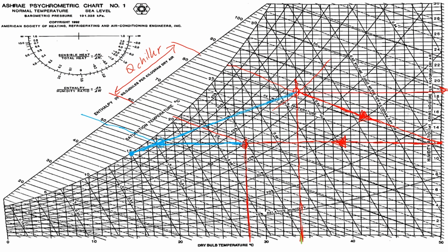Now we calculate for the second system, which is the conventional compression refrigeration. The power for the cooling coil is mass flow rate of air multiplied by delta H. From the psychrometric chart, we can see this power is here between the ambient and the coil outlet point.